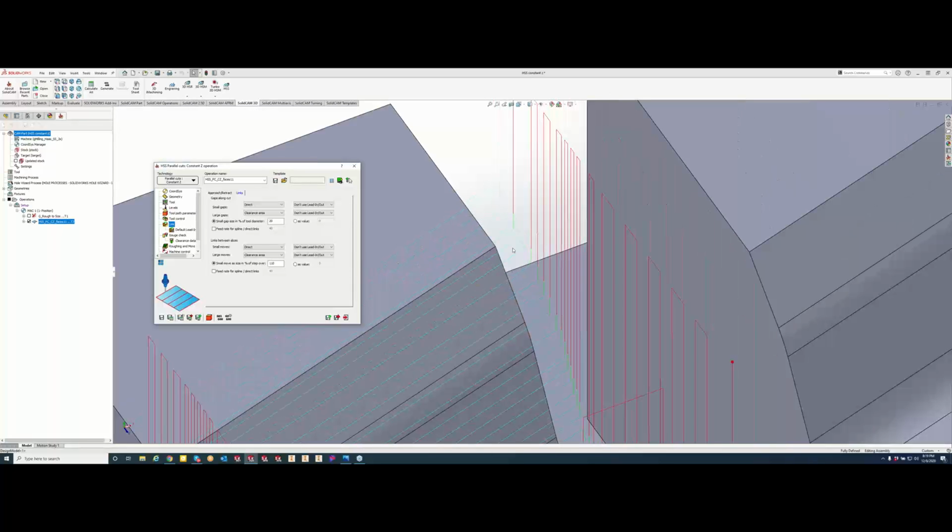But there's no point in coming all the way up to the clearance in this particular part. So what I like to do in here is, we have a lot of different features in here, but my personal favorite in here is the blend spline. So now if we go ahead and save and calculate, what the blend spline is going to do is it's going to do a nice arc working its way out.